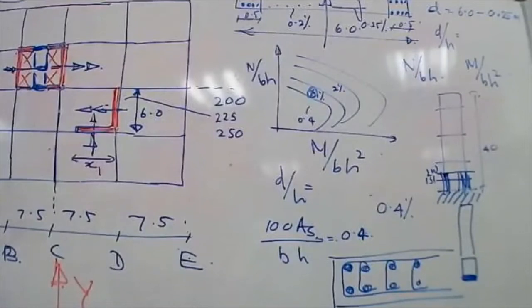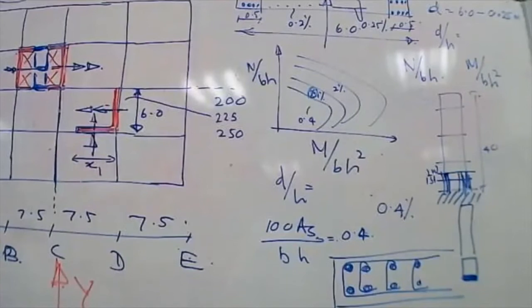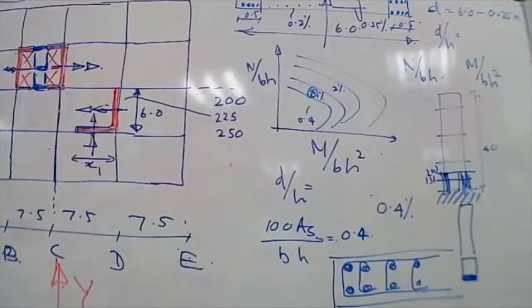You might design the same wall with 0.8 meter. Another person might design it with 0.7 meter. I would say 0.5 meter is the bare minimum. I would consider something like 0.7 or 0.8 meter. But you will not consider 2 meters, because that is too much.